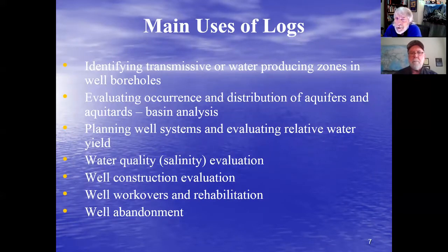The main uses of logs are numerous. It's basically only limited by your imagination. You can identify transmissive or water-producing zones and evaluate the occurrence and distribution of aquifers and aquitards. You can plan well systems, both investigation and remediation. You can assess water quality and well construction. It's also going to help you look at the integrity of historical wells, well workovers and rehab, and also moving toward well abandonment.